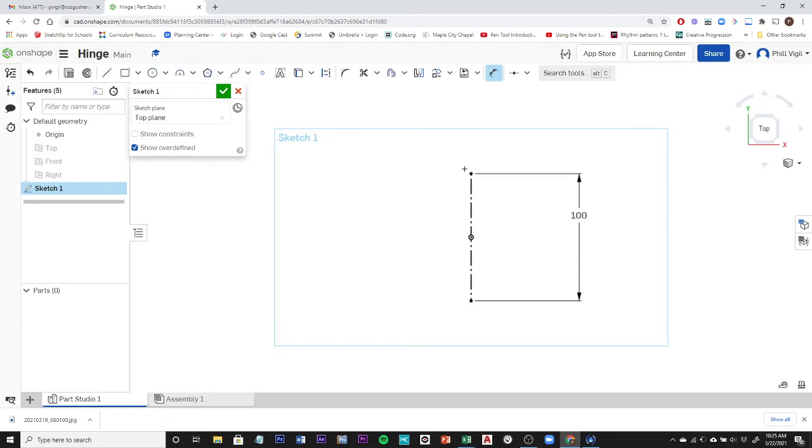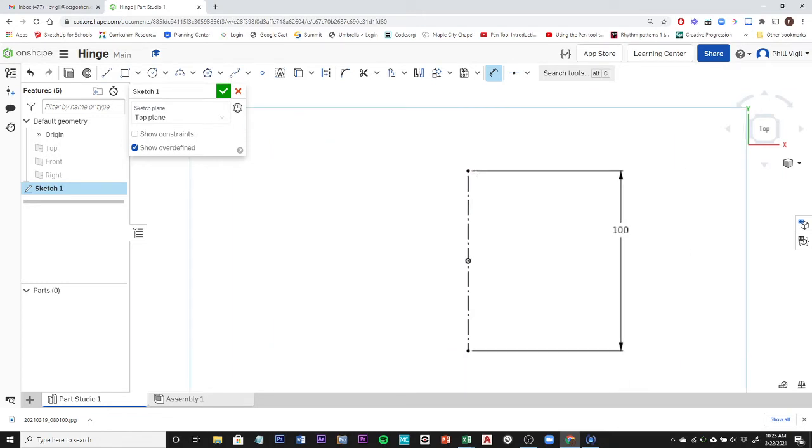Alright, now I'm going to create what I'm calling the hinge, like the center parts. I don't know what to call them, but the actual part where the hinges attach to each other. So we're going to model those using rectangles. I'm going to use the rectangle tool, click in the upper left hand corner where my construction line ends right there, and drag down and away.